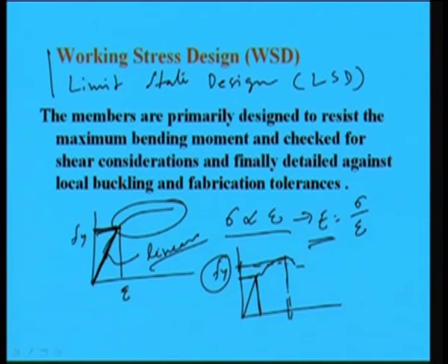So, what we are seeing is, in case of limit state method of design, the load carrying capacity will increase with the increase of some deflection. So, deflection also will increase with the increase of load carrying capacity. In limit state method of design, we have to ensure the serviceability condition, whether that deflection is okay, whether the occupants will feel discomfort or not. All those things we have to check. So, the service load, what will be the service load, all these things will come into picture. However, we are not going into details of the limit state method. We will be focusing our lecture only on the working stress method of design.